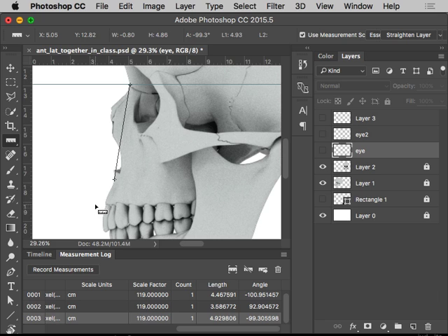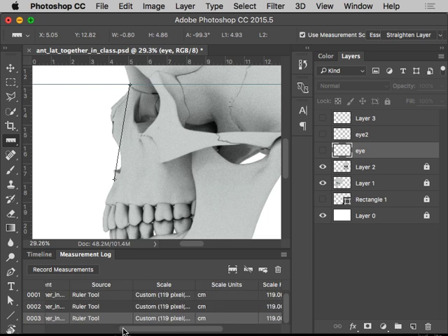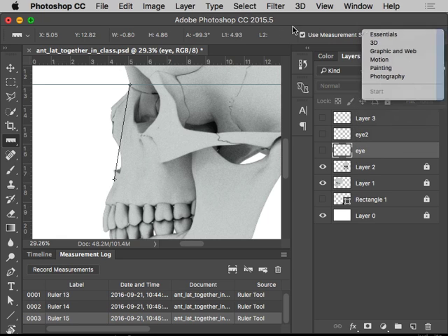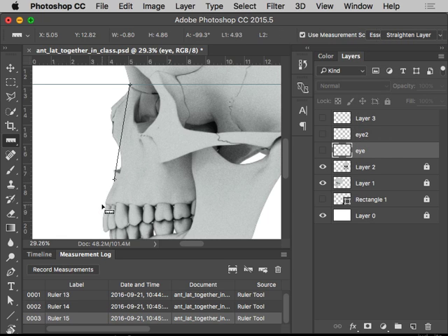So we have to put a plane that goes from prosthion to nasion. That's the nasion-prosthion plane, and that's the plane we have to make an angle from. So the easiest way to do this, there's a button to clear your measurement. But if I just start a new measurement from prosthion here and go to nasion, so there's my nasion-prosthion plane.